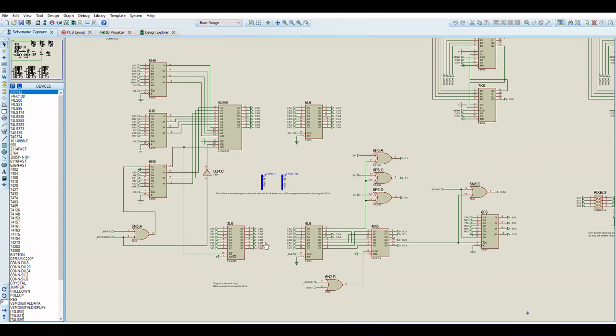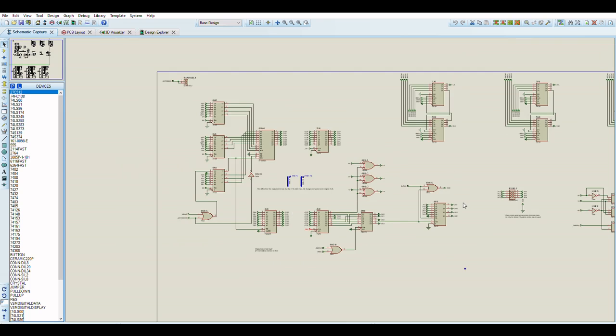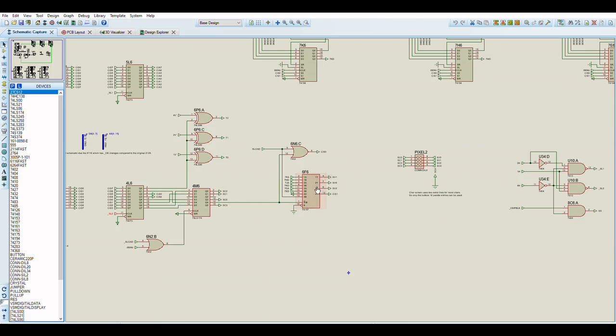And again, this decides on whether or not you're reading from the character screen or character RAM memory, and it's latching the value at the correct timed position. In this case, it's SL1 and SL2. SL1 and SL2 signals basically come from this little piece of logic here.